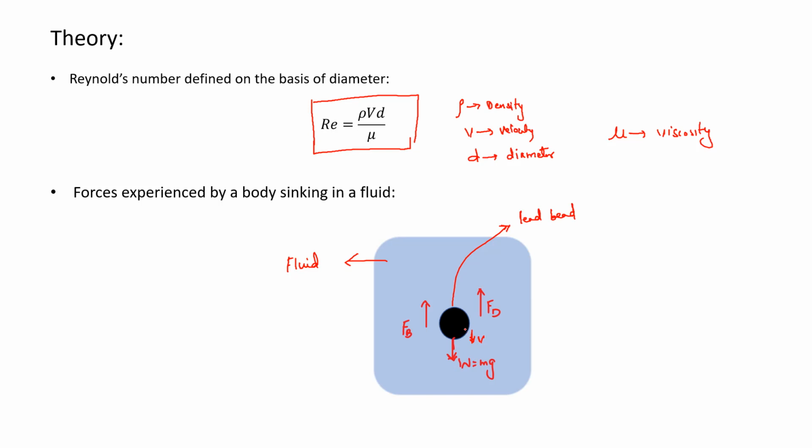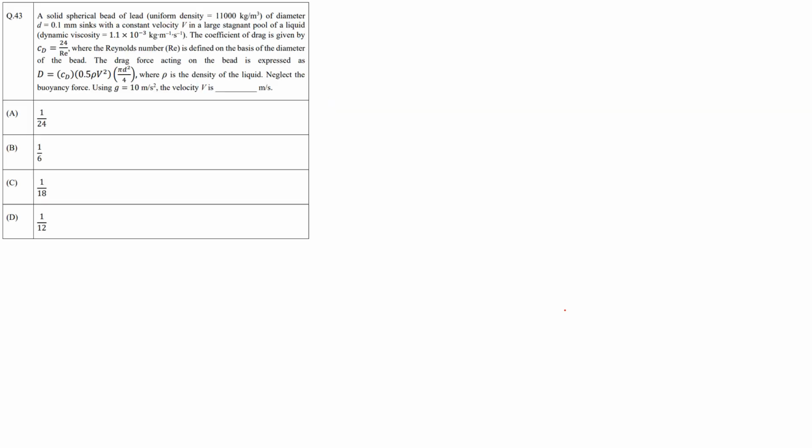W gives you the weight of the lead bead going down, and because of the fluid, this body experiences a drag force Fd in the upward direction. Also, the body can experience a buoyant force given by Fb. So these are the various forces acting on it, and let's see how we can solve this question now.